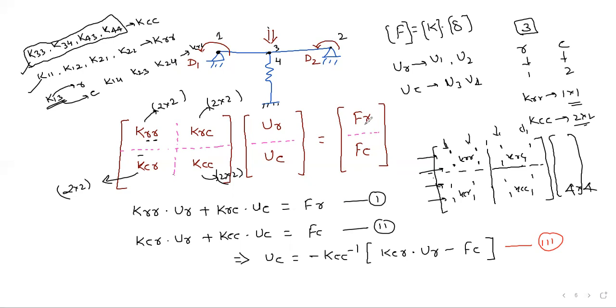In FR also we will have the same thing. In FR we will have force at 1 and force at 2, and in FC we will have force at 3 and force at 4. So this is also 4 elements. Again, whatever this matrix I have represented, this is the same matrix as we have been discussing from the basics of finite element. From the starting itself, the stiffness matrix should be of this size. By seeing the problem itself, we can test.